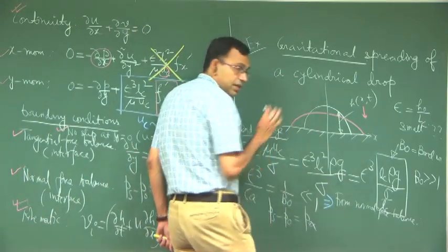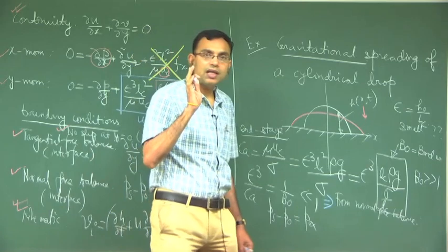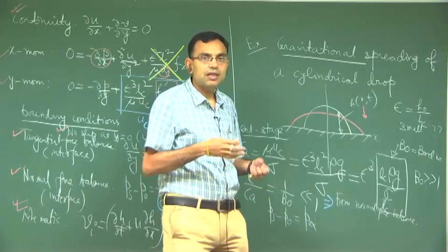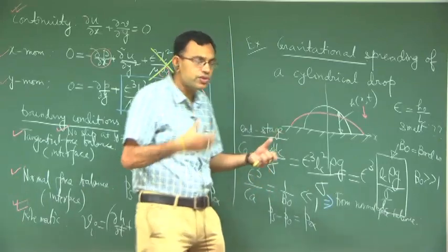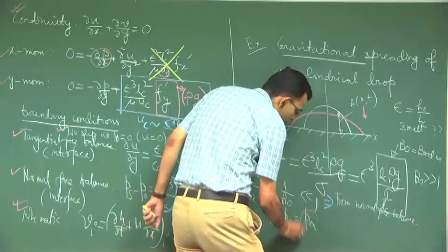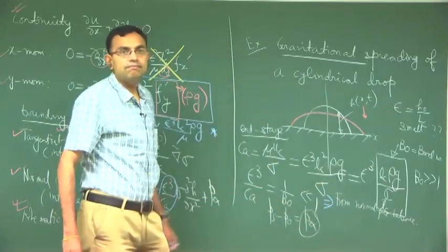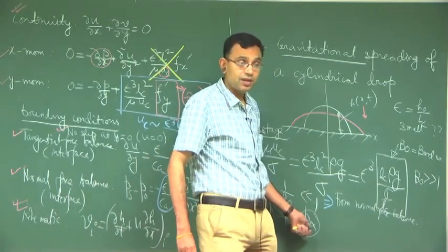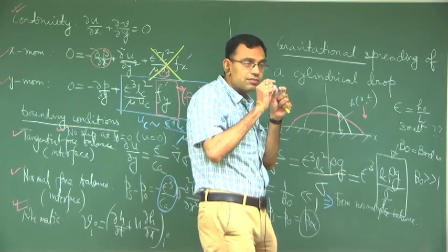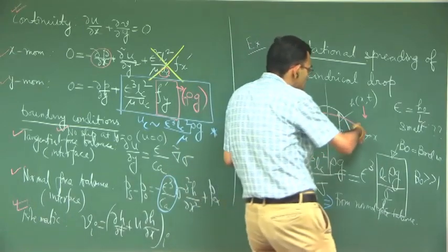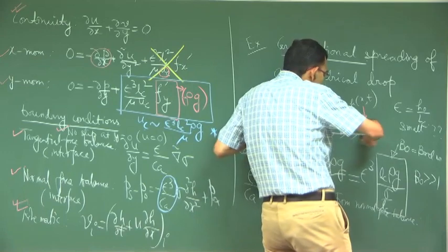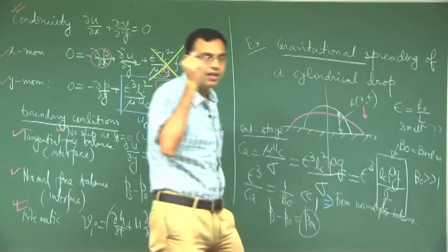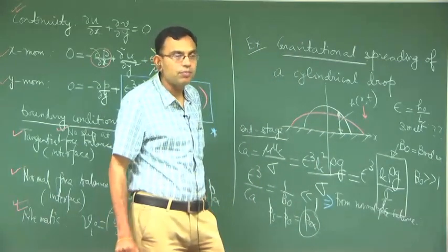Now, this is a key question, because I am illustrating it in an elementary class work where it is not to demonstrate to you research issues. I am forcefully neglecting it to simplify the algebra with an understanding that yes, this is negligible to a large extent, but in the finishing stage the droplet almost completely has its footprint on the surface, then the film thickness is so thin that van der Waals forces can actually become very important.